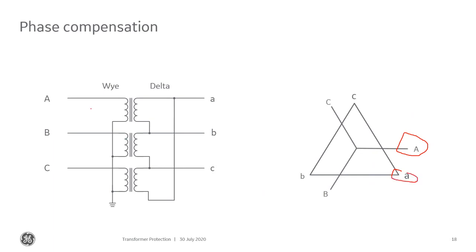Now the way that this actually happens is that this transformer here, or these windings here, are exactly in phase with the other windings there. So if we have an A that's sitting right here, what's coming out right here is exactly in phase with what's right there. But our CTs are going to be right here. So what is going to go into the CTs, and also the bushing is probably sitting right here, what's also coming out of the bushing is going to be this A minus what we see on C.